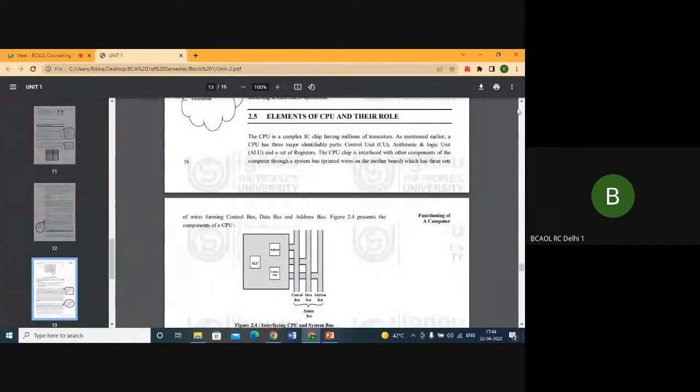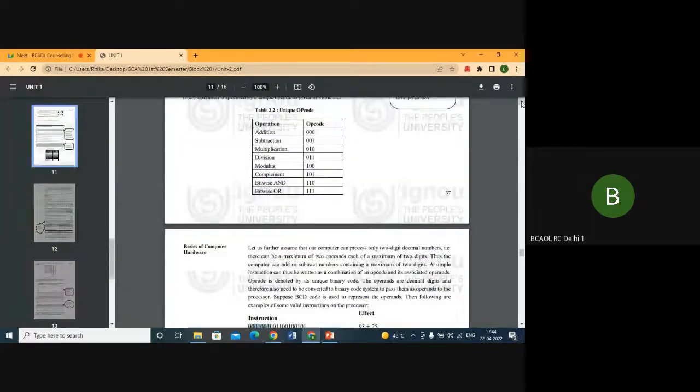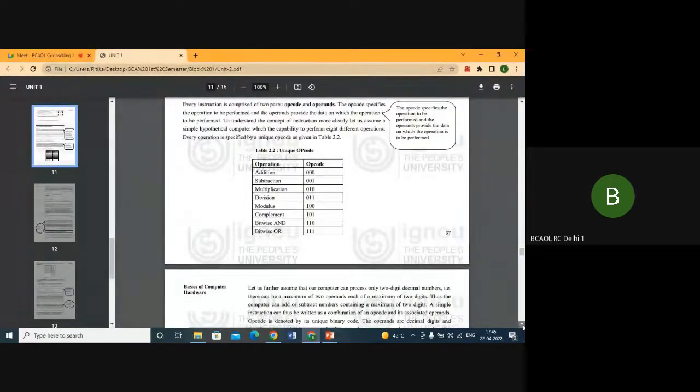So this is how it is written, basically. Then do you know what is BCD? Binary coded decimal. Anybody knows that? A decimal written in the format of binary. BCD is always each number. Suppose I am taking 93. Each 9 and 3 separately, in 4 bits, I have to give. I will not take 93 as a full decimal number and divide it by 2 and give you the answer.